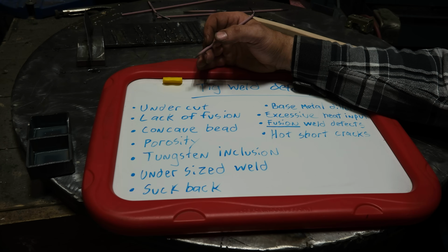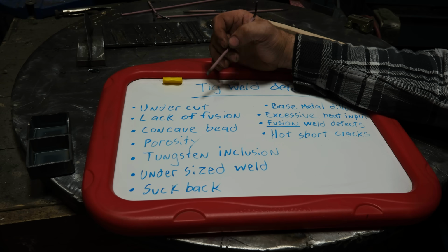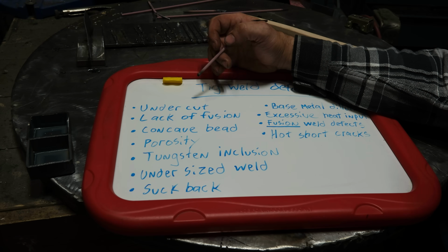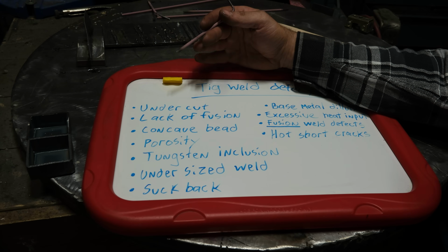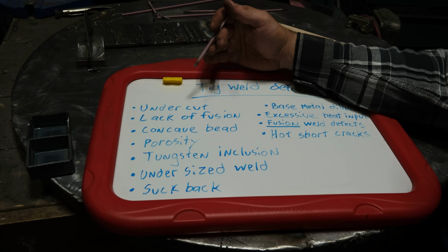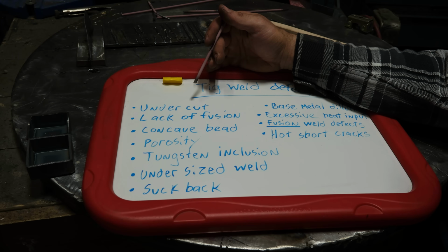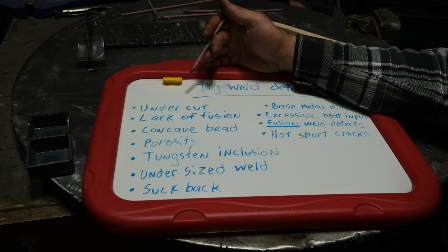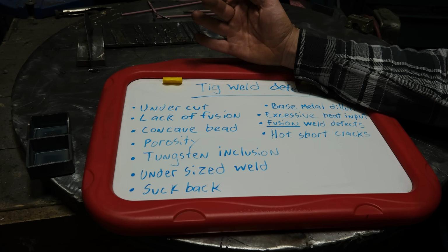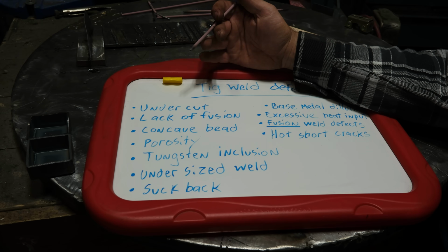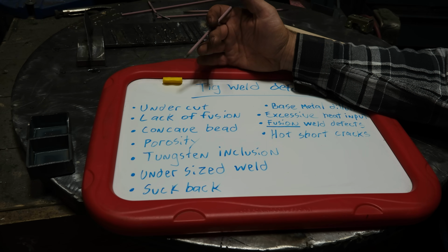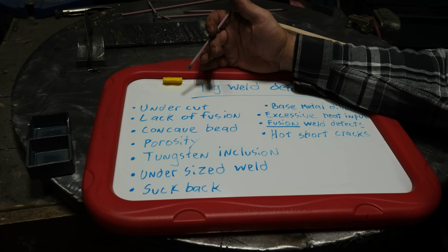And if you don't push enough filler, you will leave that scoop out of that material. And that, speaking of filler, is another way to solve undercut. If you're not pushing enough filler as you're welding, you will produce undercut. Basically, a fusion weld with TIG where you're not adding filler is 100% undercut. That's what you're doing. Well, if you don't push enough filler as you're making a weld, you will leave that scoop left behind. And again, it's undesirable simply because your base material is now thinner or has a place for cracks to propagate at. You don't want either of those.